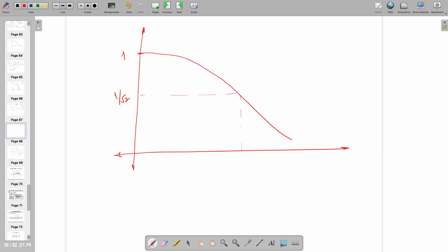If it is a second order system with minus 40 dB per decade, you are going to see this thing, or at omega 0 this thing will happen. If it is third order, you are going to see something like this, where the slope gets improved and it's minus 60 dB per decade.